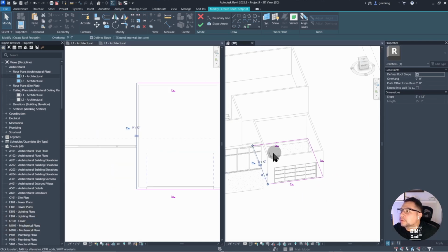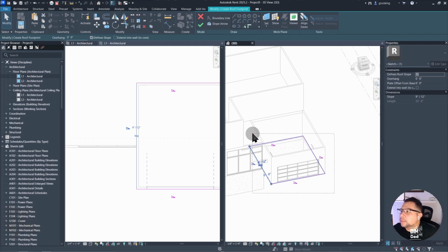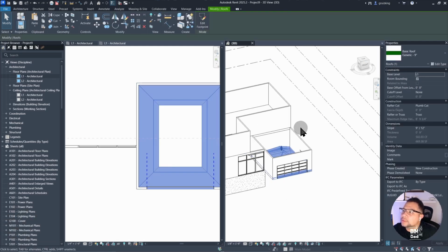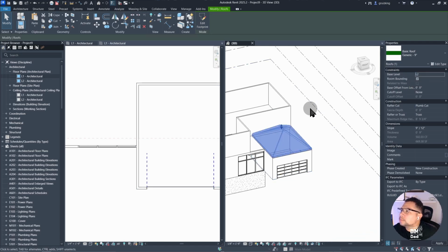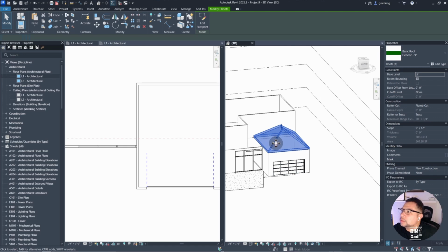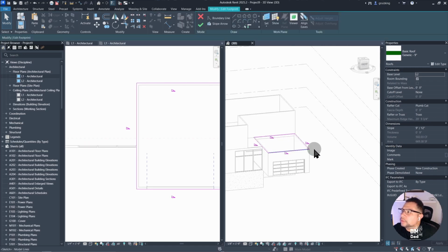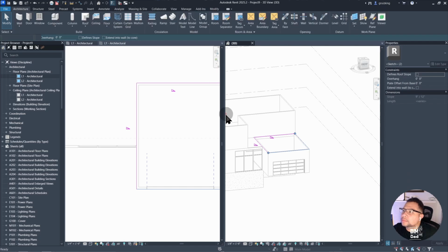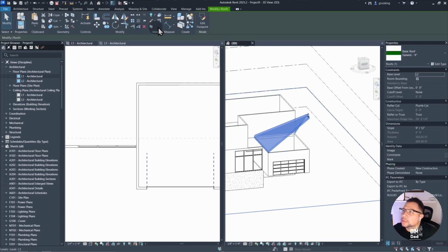Now this would be a really weird roof if I did that, so I'm going to go ahead and remove the slope indicators. Now just to show you, if I were to hit done on this, I have slopes from all directions. Oops, let's move it up. There you go. Now you can see here, if I get rid of, let's say, these two here, then you end up with something like this.